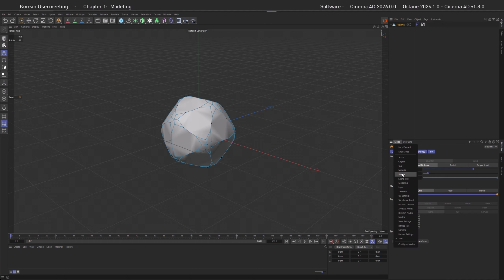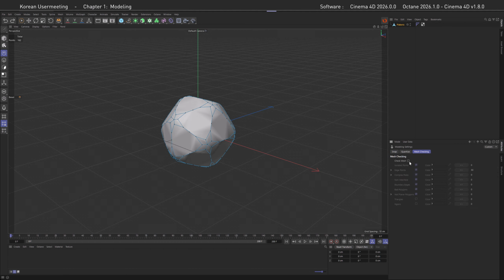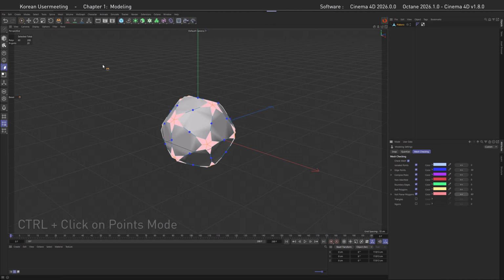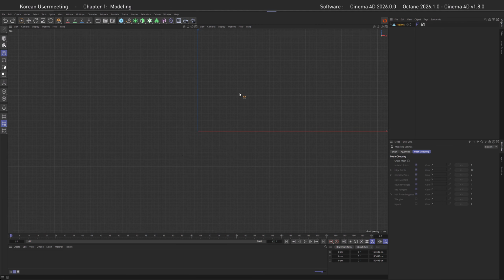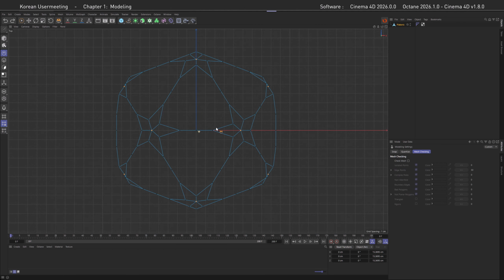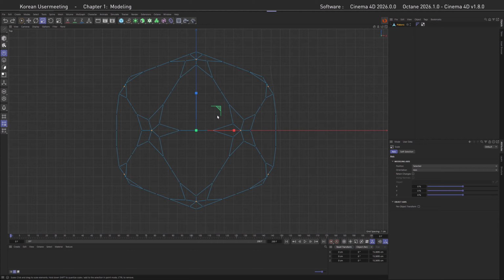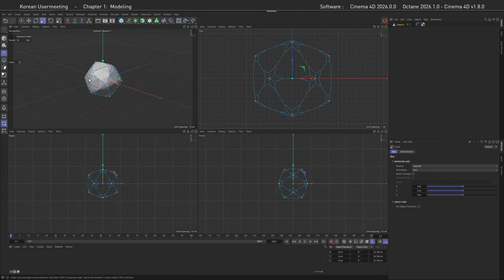Let's select the middle point of our newly created bevels by going to mesh checking mode, turning it on, going to non-planar polygons, converting it into a point selection and shrinking the selection. Here we go. Select those points because they're slightly inset and therefore make those spiked polygons around them not even or not level. So what we need to do is scale them out just a bit, 5% is enough, to make them nice and flush.